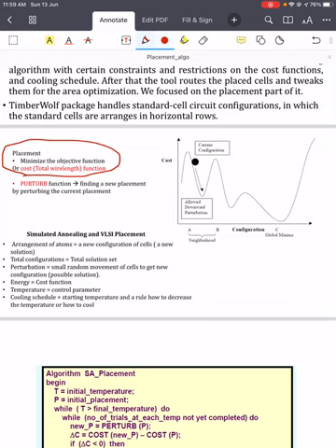These two are very general techniques that you already understood in floorplanning, where we also had perturb functions, and in partitioning, where we had perturb functions for simulated annealing. Similarly, here in TimberWolf, which is a simulated annealing based placement algorithm, we also have to define these two functions: how to calculate the cost function and how to perturb.